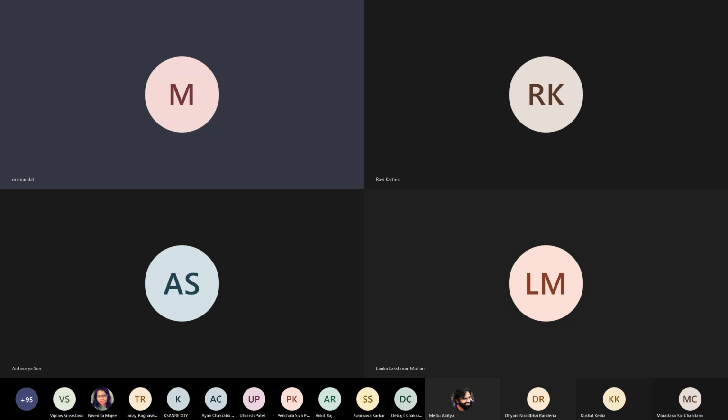So this loop, if this is X and this is Y, then these loops are in the ZX plane. Now for TE10 mode, the magnetic field is also in the ZX plane. So in this case, the coupling is through the magnetic field from the inner conductor to the TE10 mode. Okay, this is the cross-sectional view.